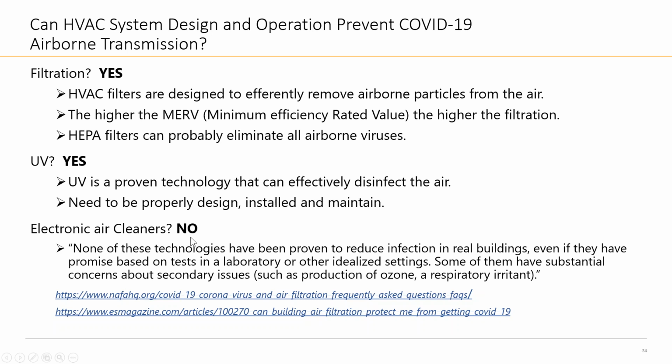Third question is about electronic air cleaners. You can look at the ASHRAE position document on filtration and air cleaning, the Jeffrey Siegel publication, the NAFA publication, and the ASHRAE website. It all says the same thing: to date, there is no proof that these devices will reduce infection.